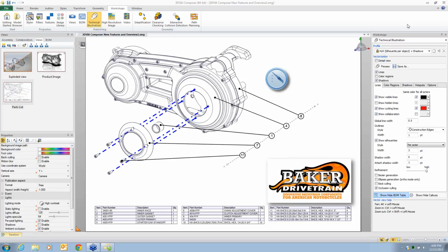Well, if you used the custom properties within the SolidWorks part, you could actually assign a part number to it when you created the part. And if you were using the property window creator, what is it called, Clay? The interface that creates the property manager or property tab. Yeah, property builder, I think. Yeah, you can use a property builder to actually create that.